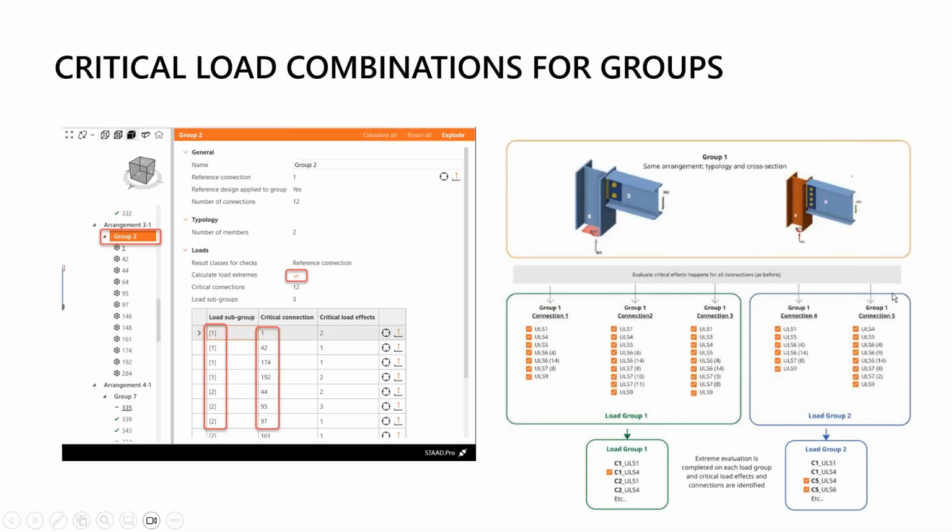Okay. All right. So one other thing to mention is that the calculate load extremes functionality is available only for Checkbot projects imported from a global analysis software. That means whenever you bring a model from STAAD.Pro, ETABS, SAP 2000, Tekla Structural Designer, Robot. So basically software where you have the loads in the model, right? So this is only available for those type of applications.